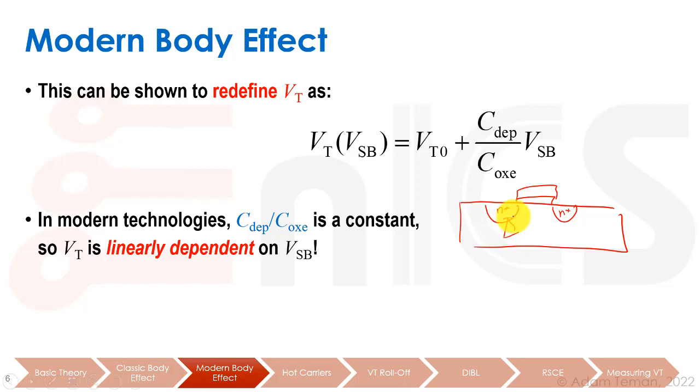So I have a diode over here, and what I know is that I need this diode to be reverse biased. And how do I get that? Usually I have ground over here, and I have something that is larger than 0 over here. It can be ground or it can be larger, and that keeps me with reverse bias on this diode, and there's no problem. Well, I always remember that I can reverse bias a diode quite a bit.